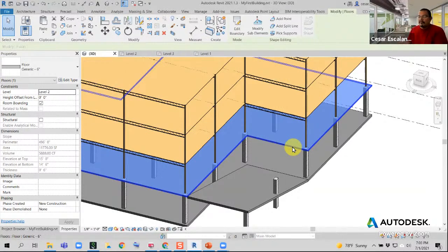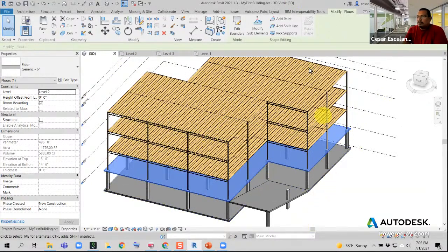but we enable just the structural floors to be visible. And the same is true with the columns. We start a project like this and we have placeholder columns. You model these columns only to a schematic design. You can put them in a single workset. And then when there's a swap of design or swap of ownership, you only display the structural link.